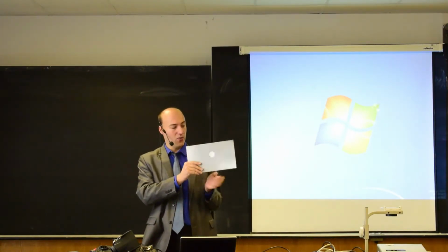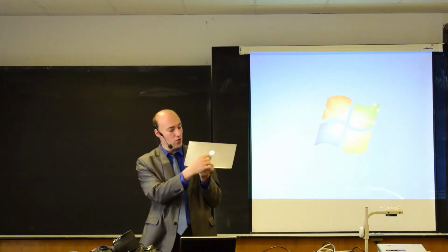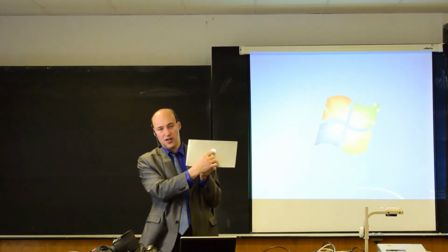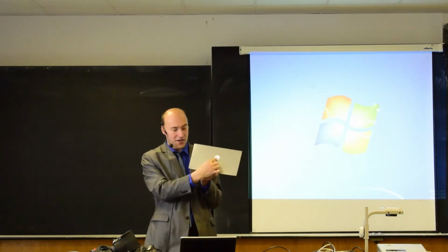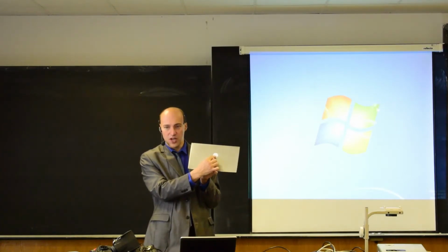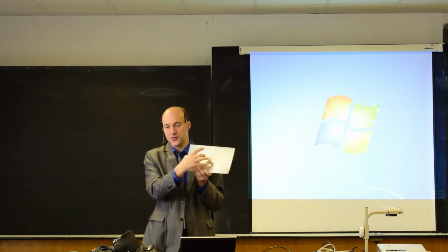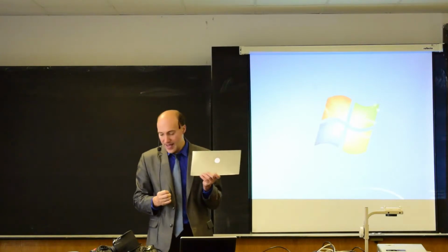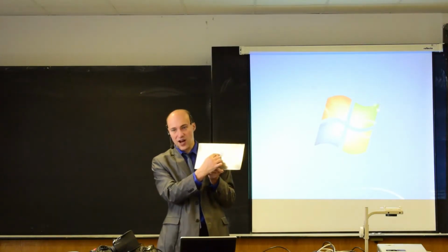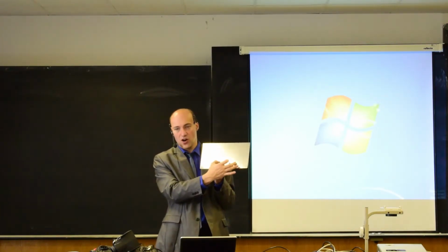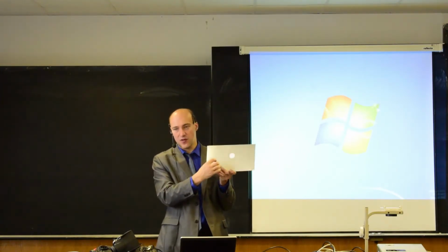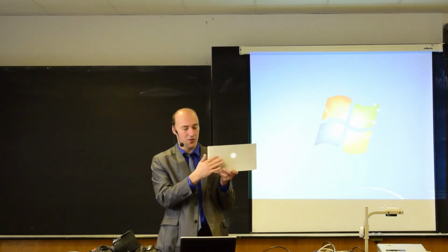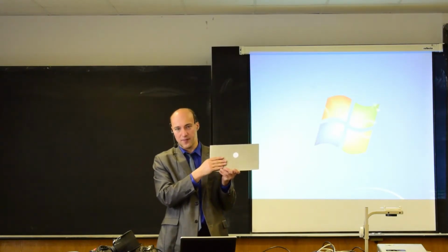And one way to do it is to glue special stickers on the object itself. And those stickers have defined emissivity. So I know the emissivity of this object. This is 0.96 for this particular sticker. And only at this sticker I could measure the real temperature of this sheet. On all other places, I get the reflection, and I will definitely not measure the temperature correctly.